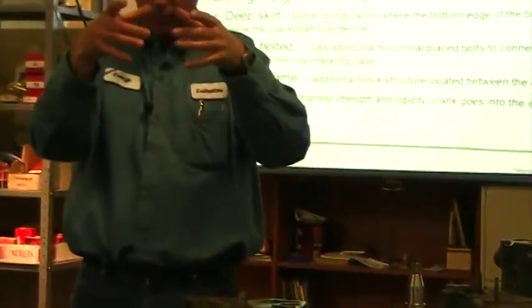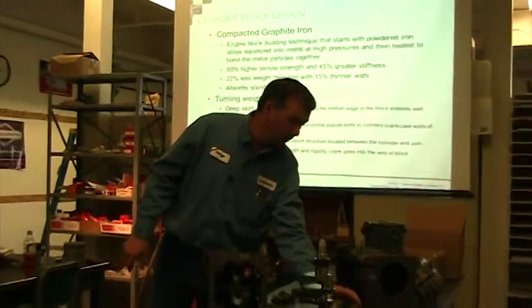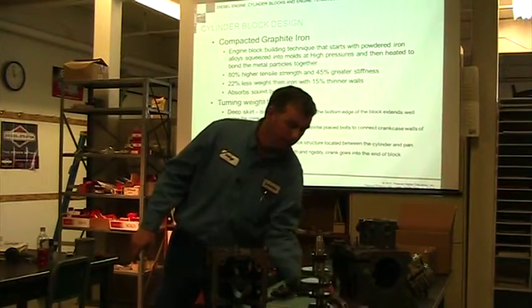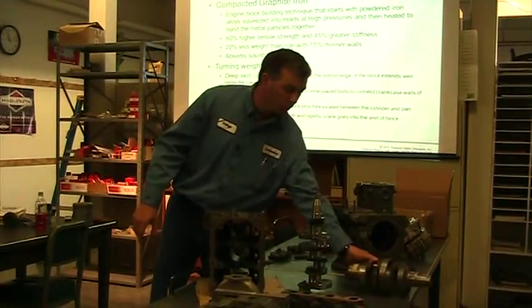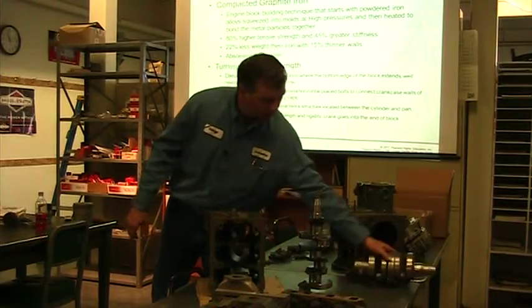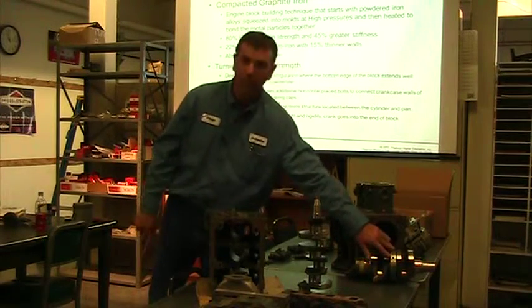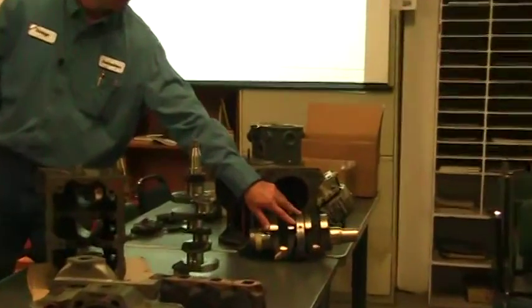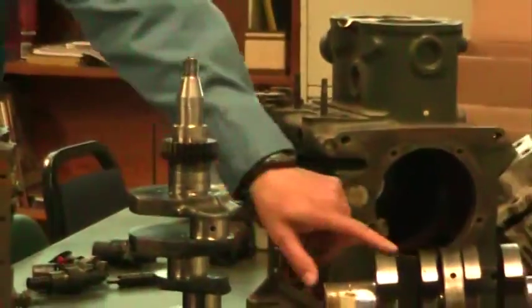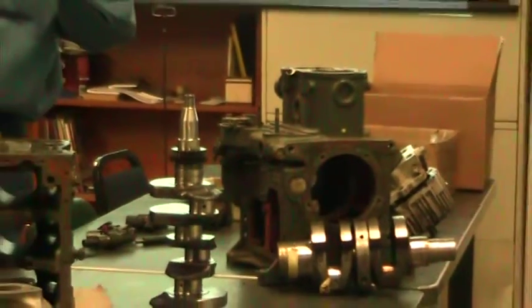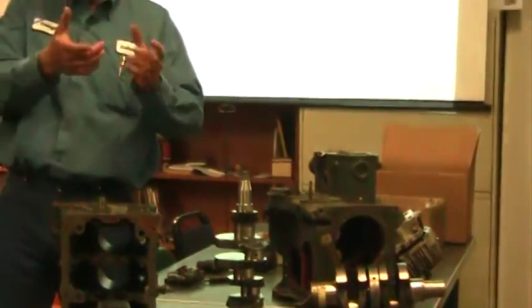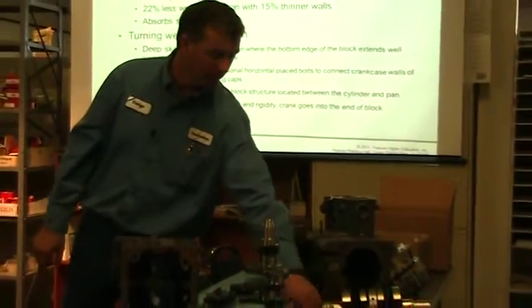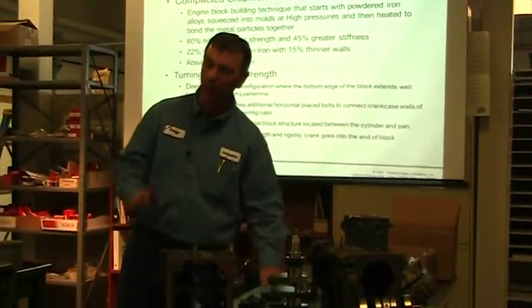And when I rotate it, there's a hole here. Can you see that? So here's a hole. And that hole, when I put this in, there's a bolt that goes up through the center. That bolt will go into this hole and keeps that bearing plate from spinning. So it's held in place by another bolt that comes up through the bottom.